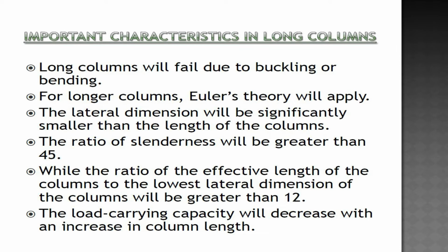The slenderness ratio will be greater than 45, while the ratio of the effective length of the column to the lowest lateral dimension of the column will be greater than 12. The load carrying capacity will decrease with an increase in column length.